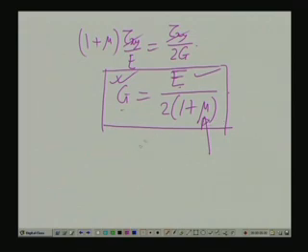Now, please note that though these three elastic constants, E, G and mu, are necessary for evaluating deformation at a particular point, out of these three quantities, two are independent and one can be evaluated in terms of the other two.